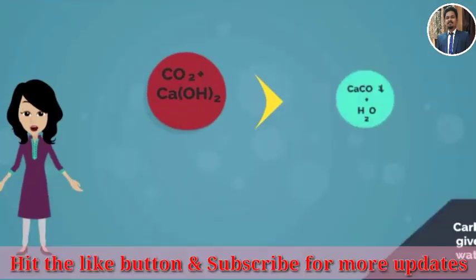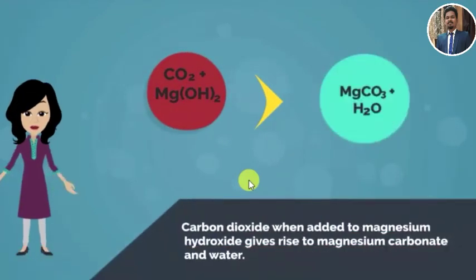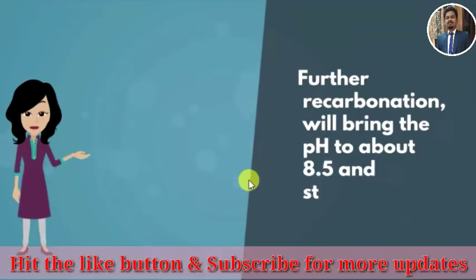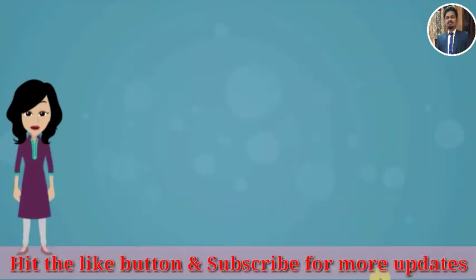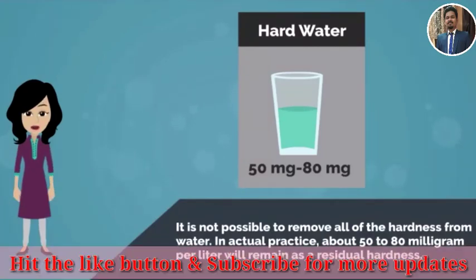Carbon dioxide, when added to calcium hydroxide, gives rise to precipitated calcium carbonate and water. Carbon dioxide, when added to magnesium hydroxide, gives rise to magnesium carbonate and water. Further recarbonation will bring the pH to about 8.5 and stabilize the calcium carbonate. Carbon dioxide, when added to calcium carbonate and water, gives rise to calcium hydrogen carbonate. It is not possible to remove all of the hardness from water. In actual practice, about 50 to 80 mg per liter will remain as residual hardness.